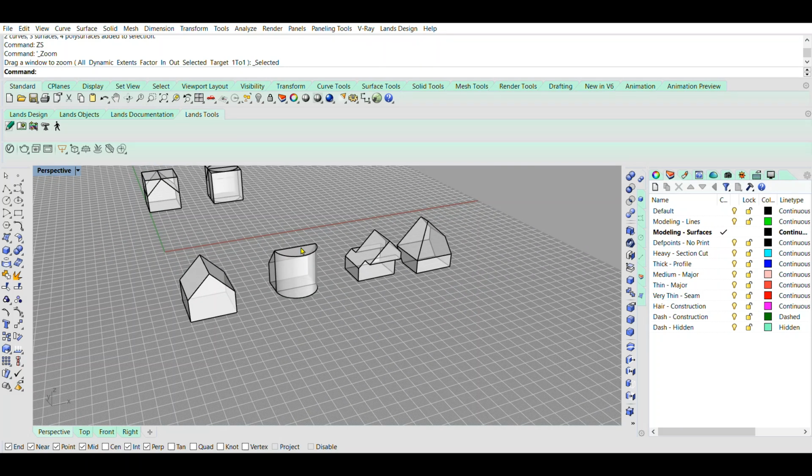So onto solid modeling. We're going to start by making some cubes to make these geometries. The first cube we're going to make is 4 feet by 4 feet. So we're just going to start off by making a rectangle. We can also just draw a box, but for this example, we're going to draw a rectangle, or we can also draw a polyline.